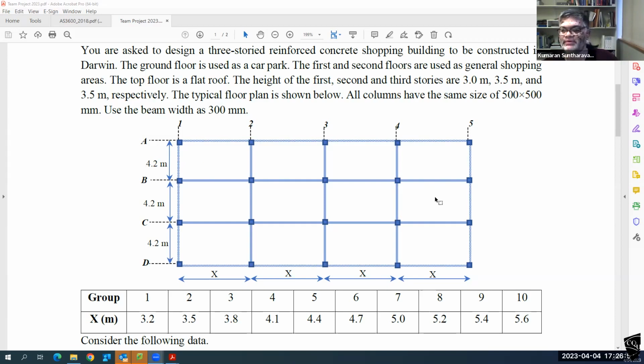Each panel will have different deflections because each has slightly different continuity. This panel is continuous on this side and this side, but nothing here and here. This corner panel doesn't have any slab on two sides, but is continuous on only two sides.